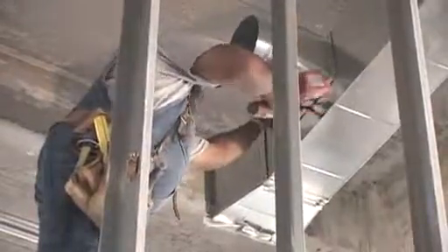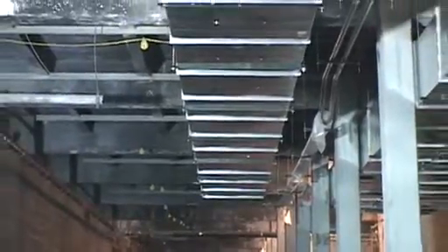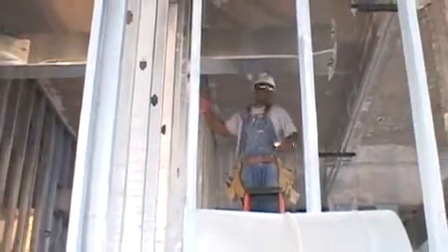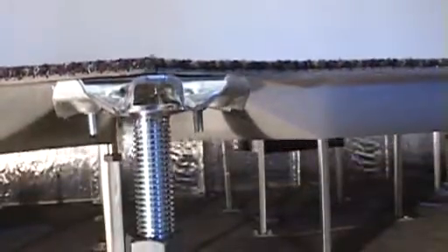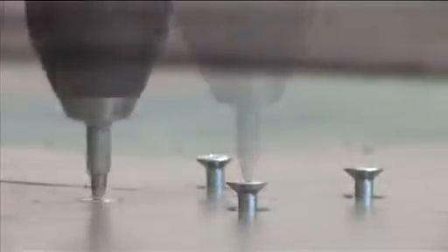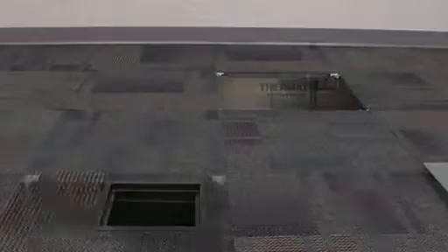Ducted overhead air often requires removing and replacing the rigid ducts, VAV terminals, and diffusers to suit reconfigured space use, which is labor intensive, not to mention the effort of doing this above a ceiling. With underfloor air distribution, the floor tiles are part of the HVAC system and are much more durable than typical ceiling tile. The swapping of floor tiles and diffusers is much easier and provides major cost-saving opportunities.